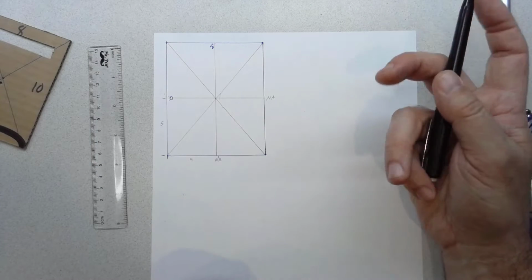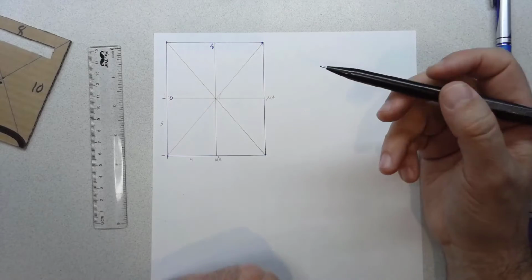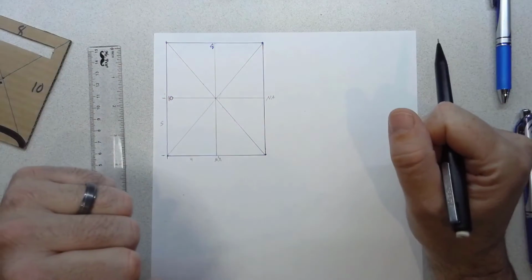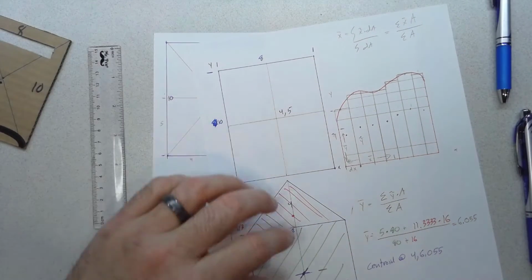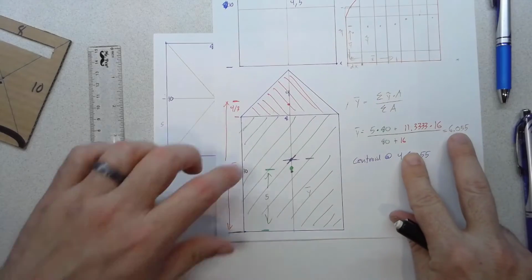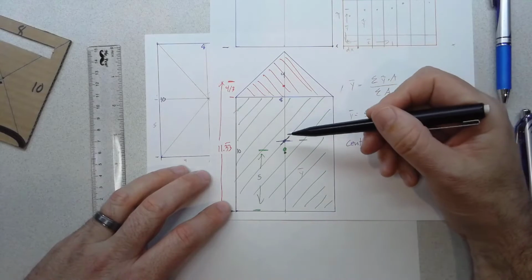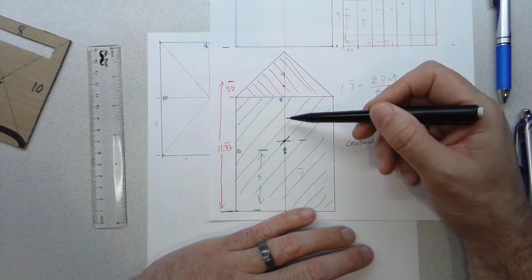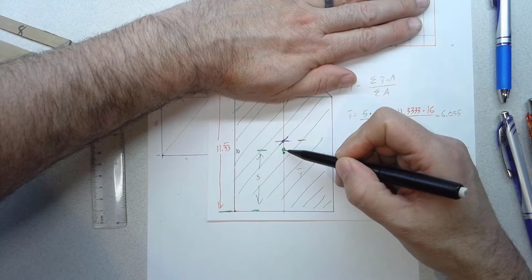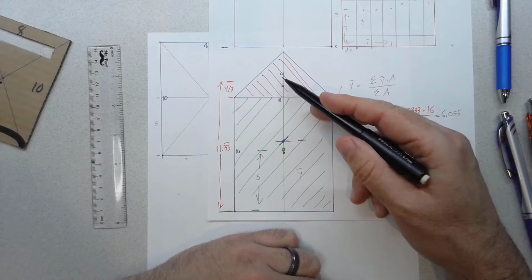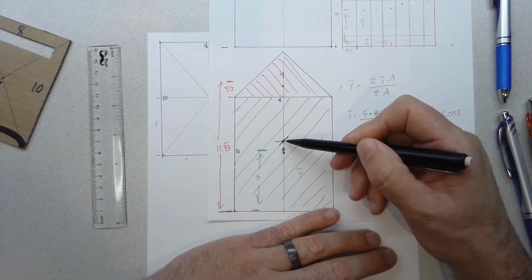We, in the last video, looked at, okay, what if we want to go beyond that into more complicated shapes? And we talked about how we can use composite areas to find the centroid. So we looked at some areas, starting out with a basic rectangle, then we added a triangle on top of that rectangle, and look at how does that shift the centroid. Hopefully you remember it. Basically, if we had our original rectangle like this, and that centroid was here in the middle, when we add on some material to the top, we're going to have to shift the centroid towards that additional material to keep everything in balance.